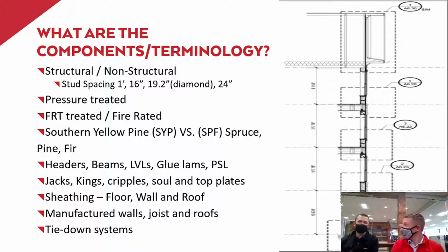So Derek, something that I've seen a lot on projects recently is it's calling out for a PSL, but the framer tries to just throw in a stud pack. Absolutely. Can you talk on that and why it's important to actually do what we're supposed to? So the difference between a PSL and a stud pack, which is something framers will do if they can get away with it because it saves them a lot of money: PSLs are much more expensive than 2x4s, and that's for a reason. PSLs have the capacity to carry much more load in a smaller format.